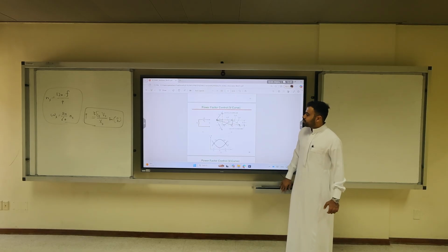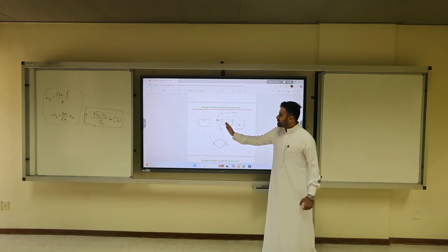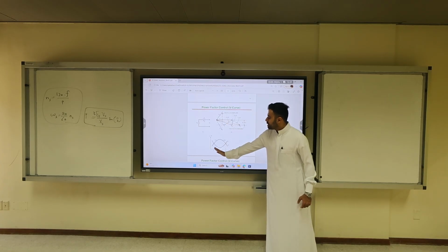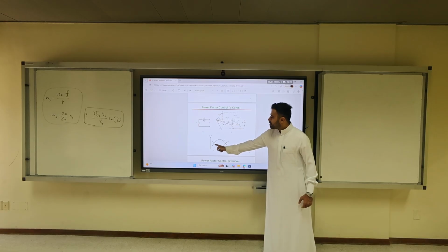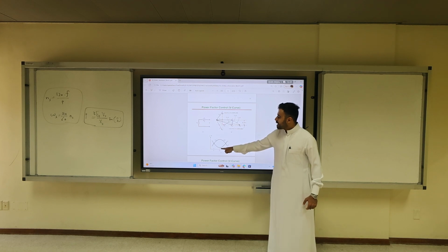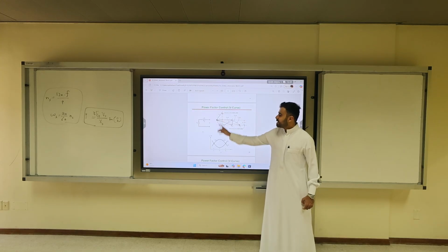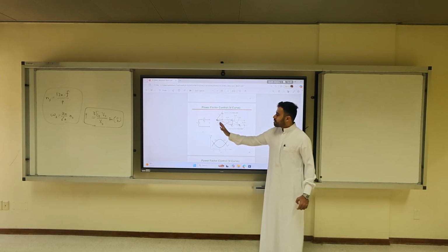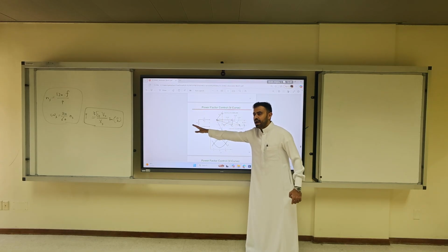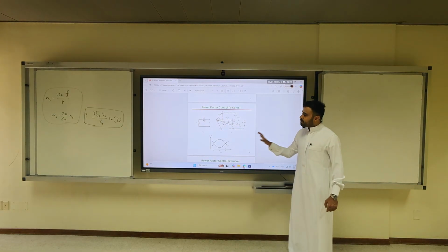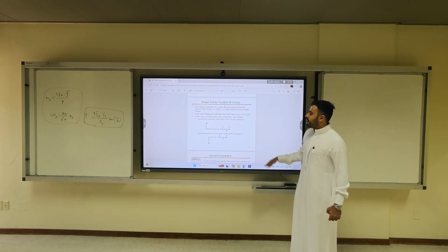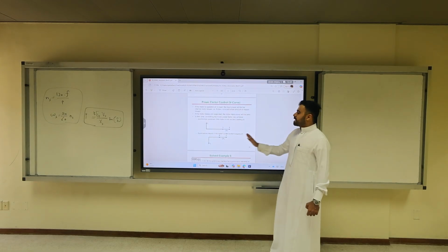For example, if you run it as an underexcited synchronous motor, you will be at a lagging power factor, but it's lower, with high Ia. Up until you reach normal excitation, you get the smallest magnitude of Ia, and your power factor is 1. Then if you become overexcited, your Ia becomes leading, and now the whole synchronous motor would act as a capacitor. So this is a very important application in real life. And here is the representation.